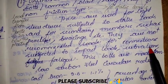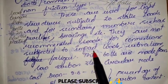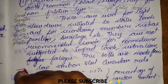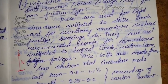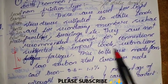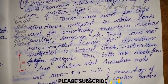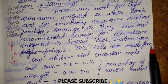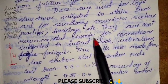They are not recommended for connections subject to impact loads, vibrations and fatigue. Whenever I say impact loads, remember it is the load that acts from a certain height. If this is a member and the load is dropped from a height, we call it an impact load. We know vibration. Fatigue is repetitive loading. On bridges, whatever vehicular loads we get are repetitive loads, and that is fatigue. These bolts are made from low carbon steel, and that is why, to resist all these loads, we are not recommending them.